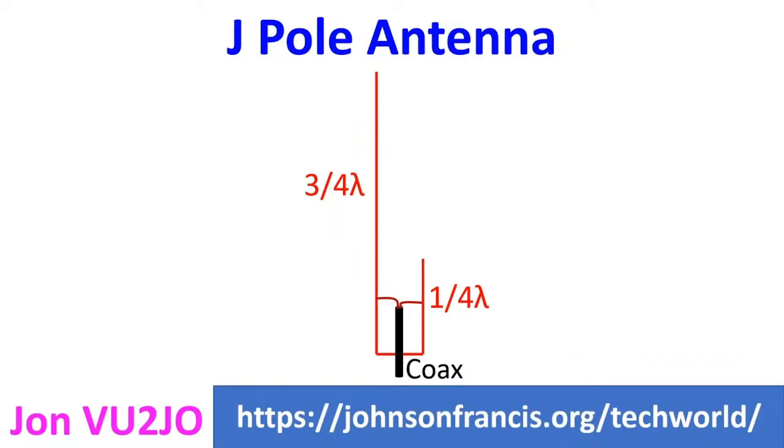J-pole antenna has a gain of about 2 dB compared to a quarter wave ground plane antenna. The gain is slightly more on the side of the J stub compared to the opposite side. Parallel conductors of the J-pole antenna should be kept away from other conducting material by a distance of 2 to 3 times the spacing between the conductors. Best performance is obtained by having a non-conducting free space between the antenna conductors and the mounting structure. Separation between the two conductors should not be more than 2% of the wavelength.